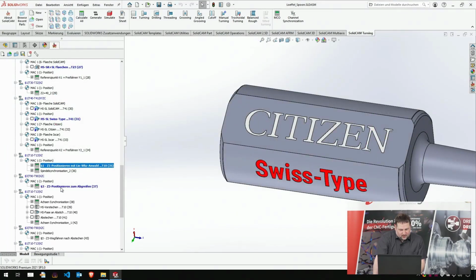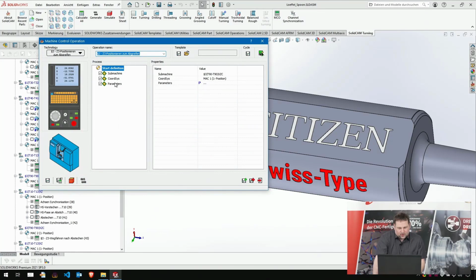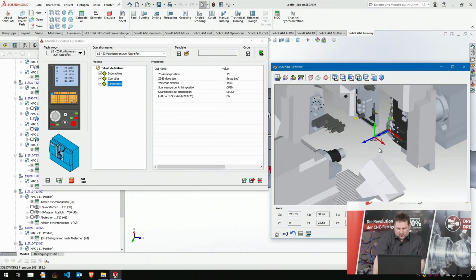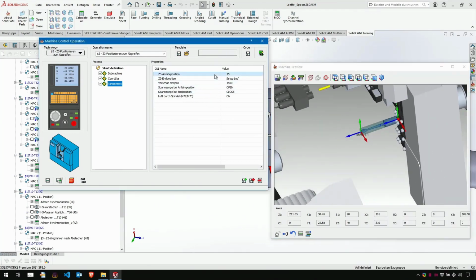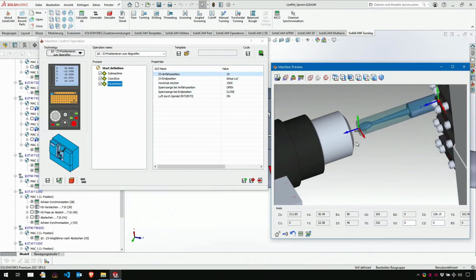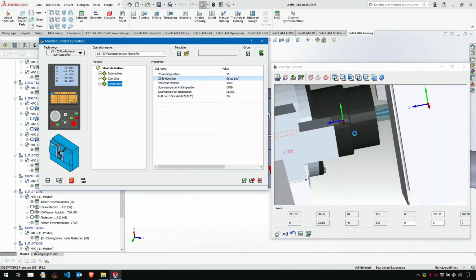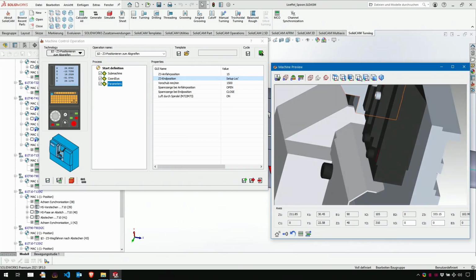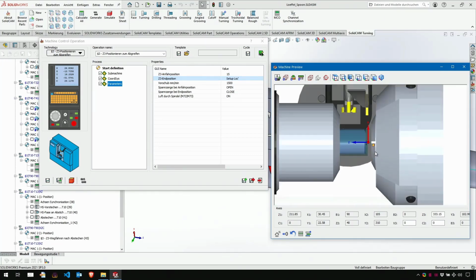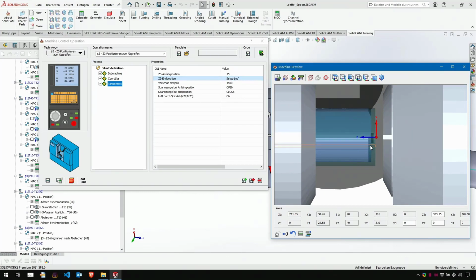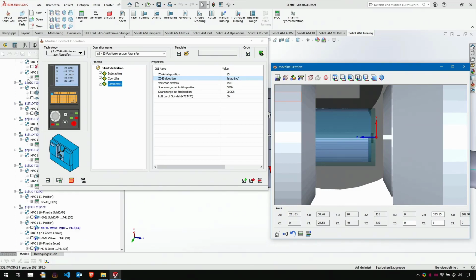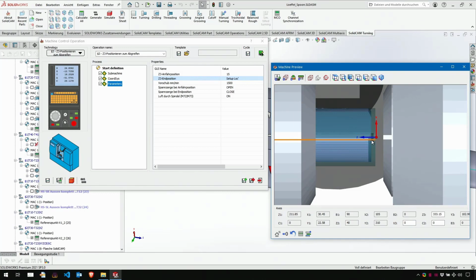We have an additional MCO machine control operation for the part pickup with a sub-spindle. Here, pre-positioning 50 mm in front of the part, and then go to our part pickup position. If we look from underneath the machine, we have here our setup location, which is defined in the setup, our 20 mm.